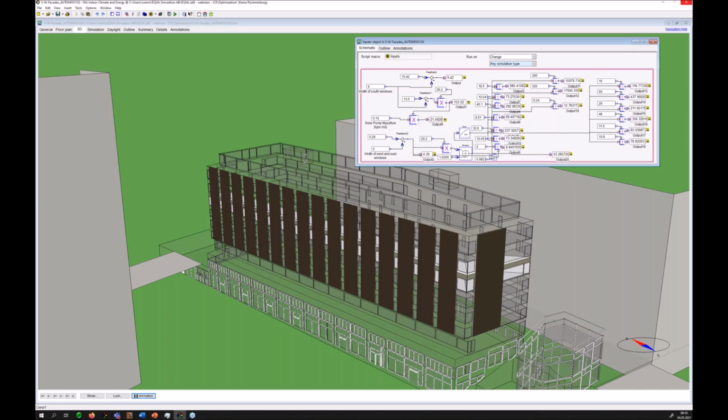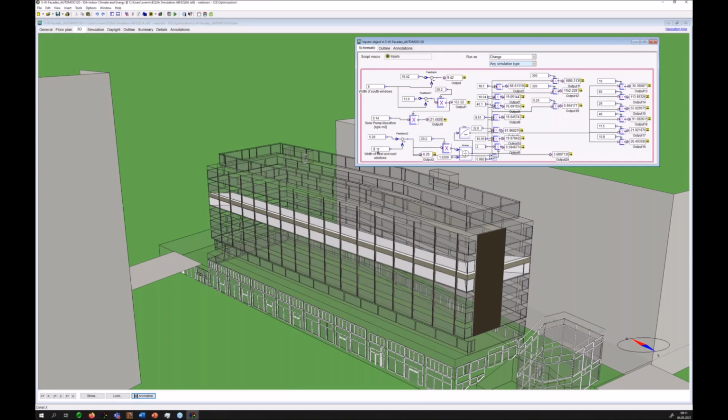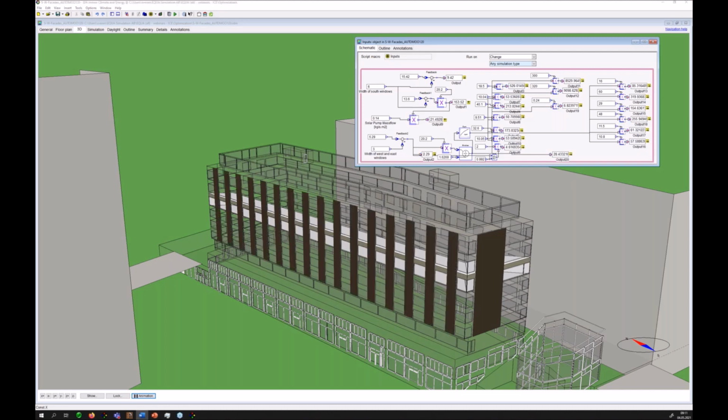And you see some time is needed for this calculation here. So let's switch back to a medium window width. Of course, we expect a direct correlation of this parameter with the amount of solar power produced annually, but also with the power consumption for the lights, for instance, in the offices. And both those have an influence on our first objective function, the self-sufficiency for electricity. So that's a number that tells us what proportion of the total electricity consumed could directly, so at the same time as production, as consumption, be taken from on-site electricity production.